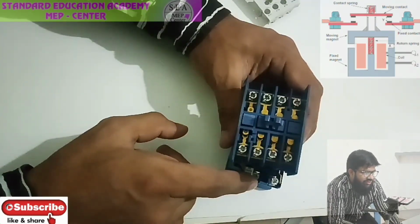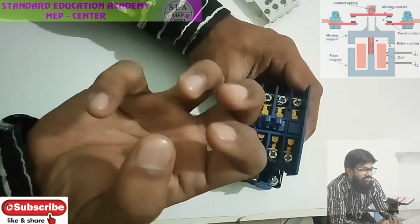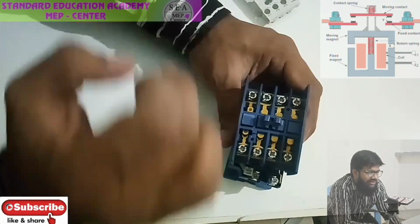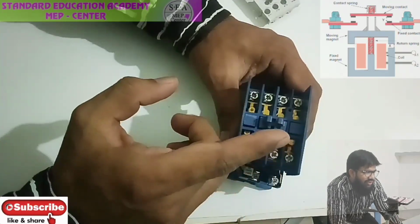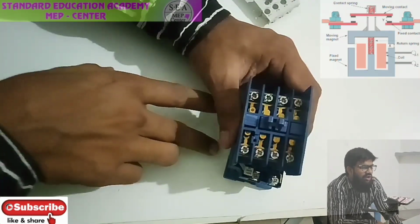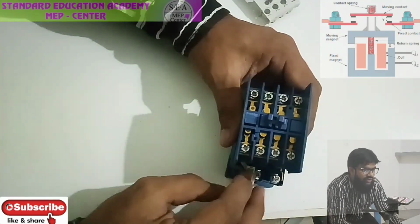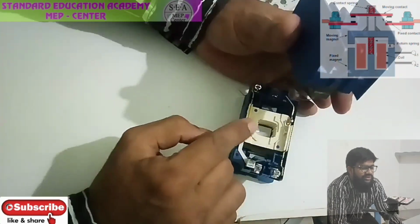First important thing, energize the coil. Due to energizing of the coil, the fixed part will attract the movable part. As the movable part and fixed part come in contact, the links will be created from L1, L2, L3 to T1, T2, T3. That's how a contactor turns on and turns off a three-phase device with the initial supply of a single phase, which will be given. That is the phase and the neutral which we are giving to the coil. As we give one phase and a neutral, this particular coil gets energized.